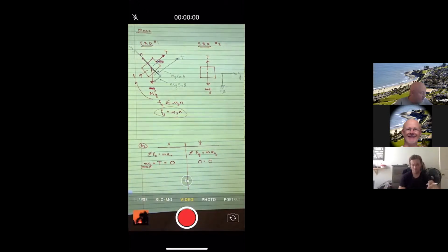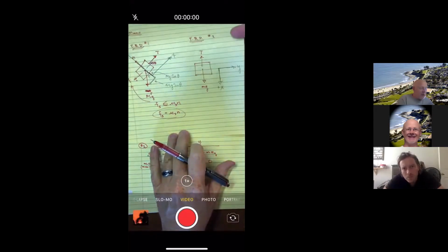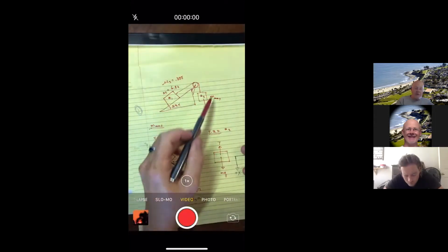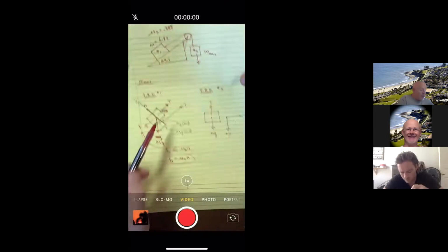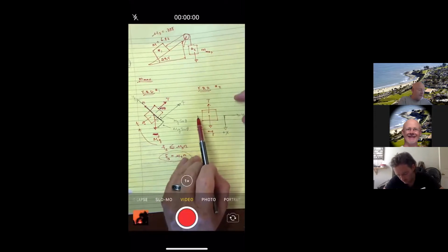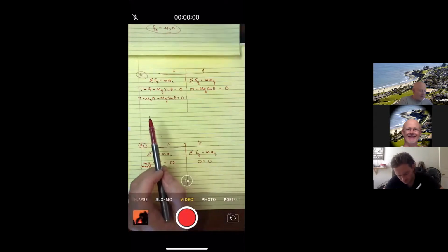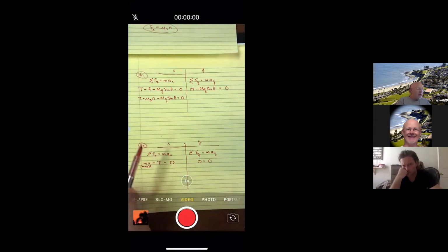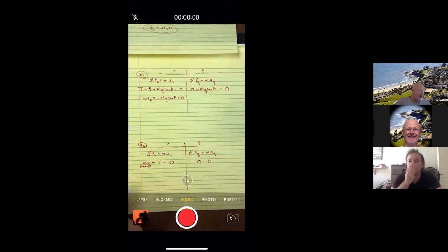All right. So I'll say it again just to kind of drive my point home. But to me, there's 4 steps in this problem. Step 1, good physical picture of what's going on. Step 2, good free body diagrams. Step 3, and that's what we just did on this page, is to write out the equations from Newton's second law associated with this free body diagram. And now we can actually then do the last step, which is solve.